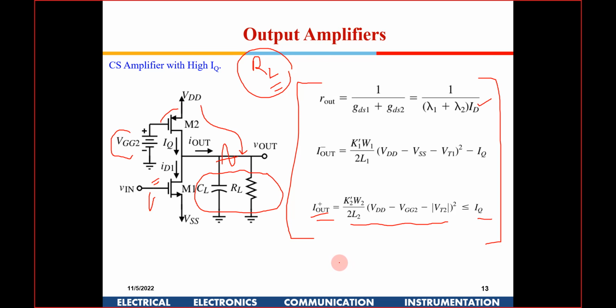Sir, how does that sizing impact the output? If you don't size it, then we will not be able to pull that much current into this load. When we want almost VDD to minus VDD swing here at those loads, then those kinds of currents will be required. So, sir, which one should be larger in size, M1 or M2?